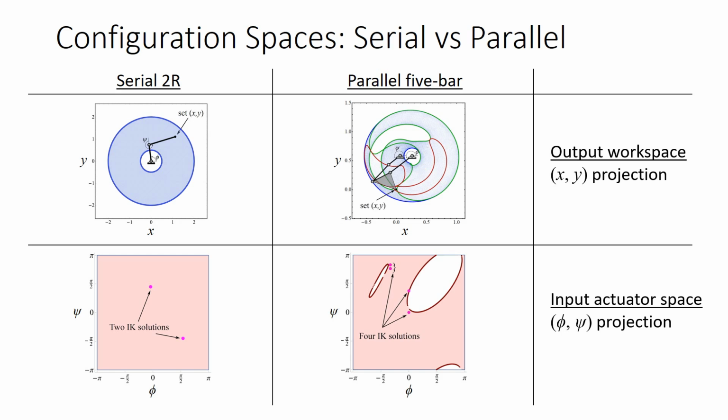At input singularities, the configuration is a bound of the input space, and the semi-axis of the velocity ellipse tends toward infinity. In that direction, the manipulator is unable to exert force. At input singularities, the mechanism suffers from force transmission problems.